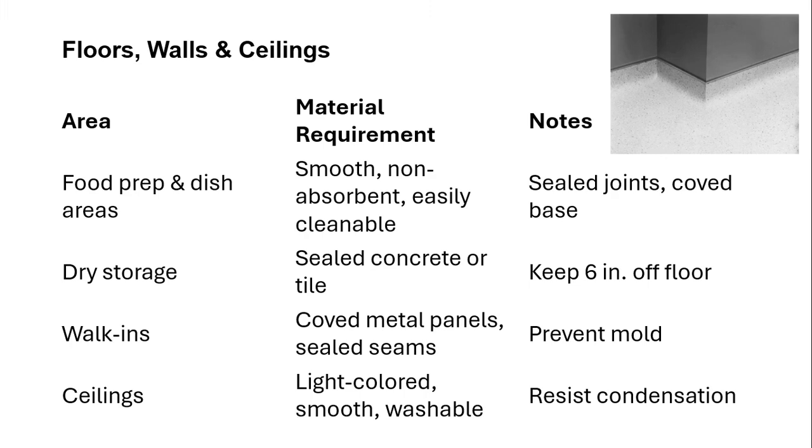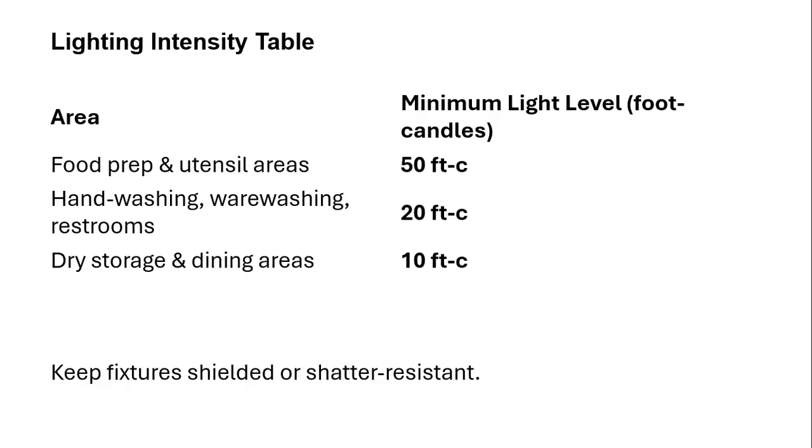We shouldn't have grease and condensation dripping down off our ceilings or oozing down the walls, because our ventilation system should be strong enough. That's generally the reason why we see things like that. If you have significant amounts of condensation building up on walls and ceilings, it's normally because our ventilation system isn't strong enough or it's not working properly.